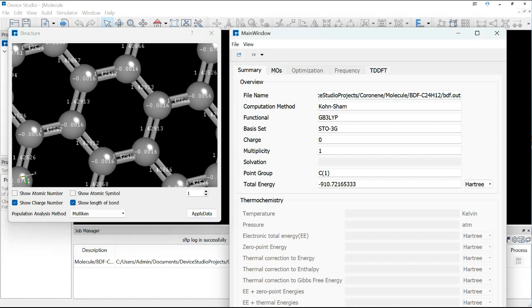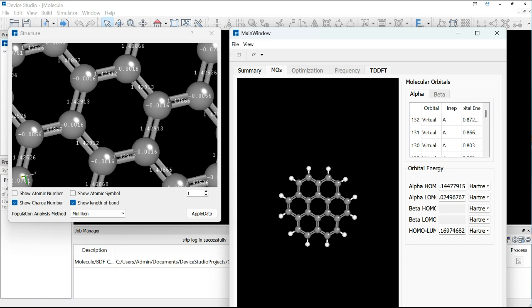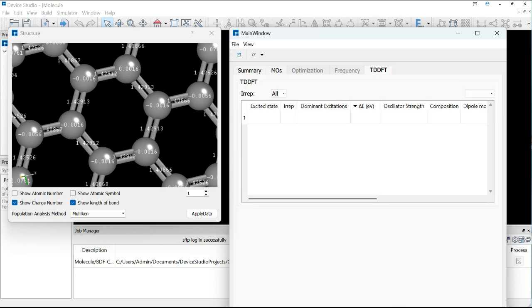And in here you can check the summary of the total energy in Hartree and electron volt, as 1 Hartree equals 27.2114 electron volt. The energy here is negative, that means electrons are bound to the nuclei, and if they have more negative energy, that means the structure is more stable. Molecular orbital structures, and the calculations do not come here for TDDFT because we are not going into the TDDFT result. After this tutorial, I will show how you can calculate time-dependent density functional theory results.